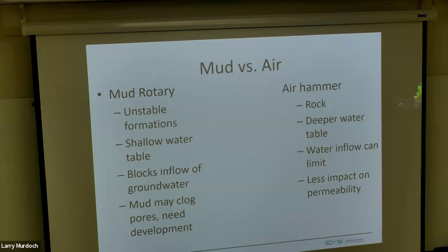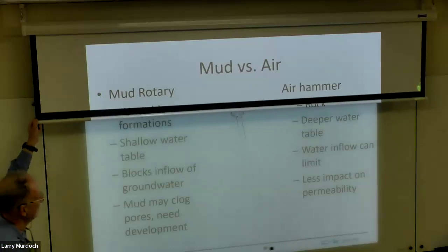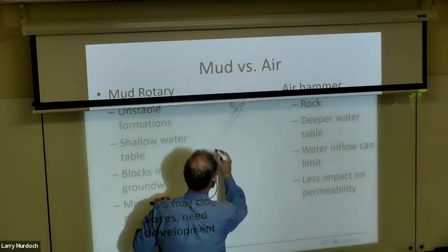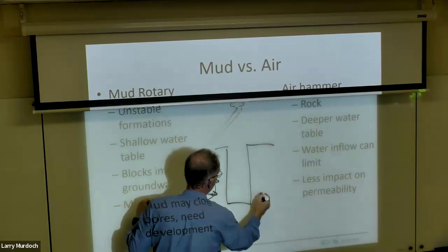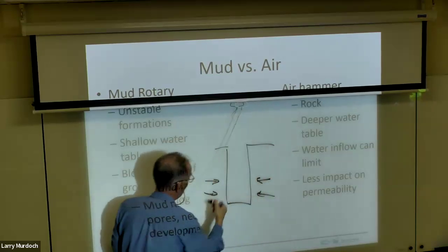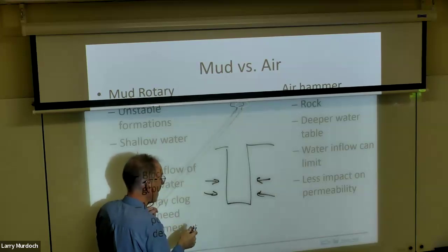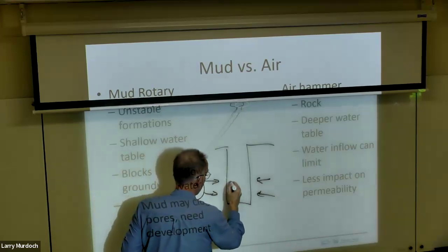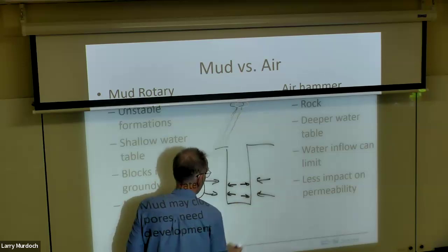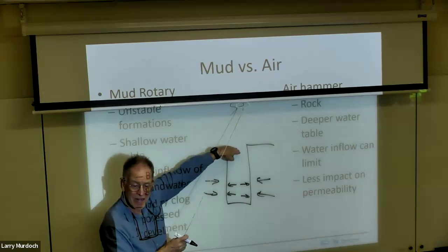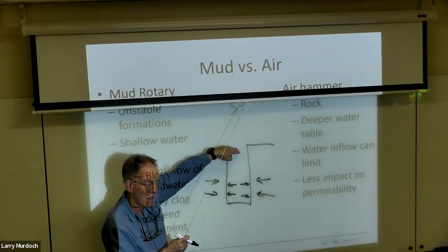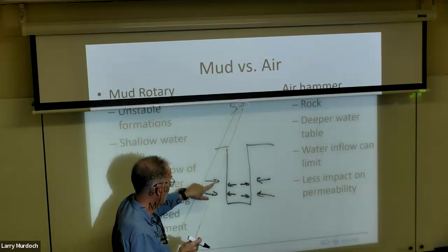So if you're drilling a deep hole, the stress in the rock is going to tend to make that hole come in and collapse. So you need to have something to counter that. And if you put water in there, that creates hydrostatic pressure, right?